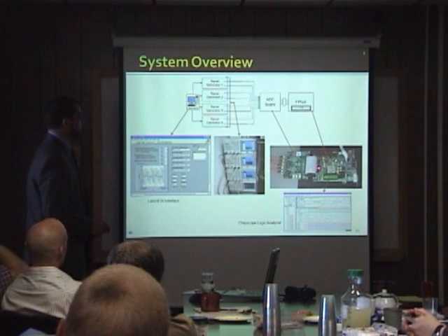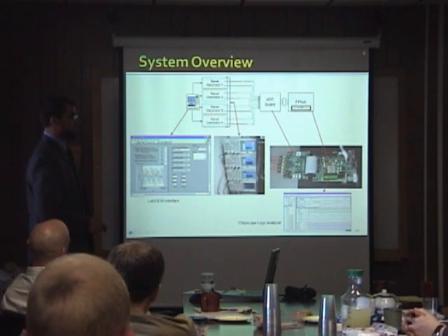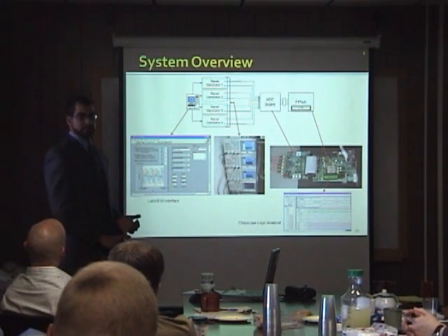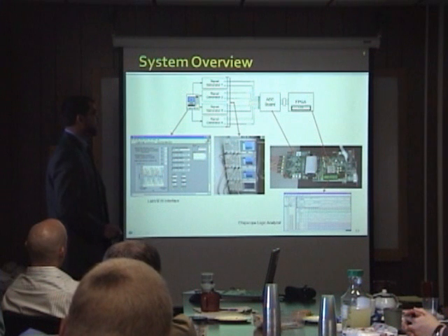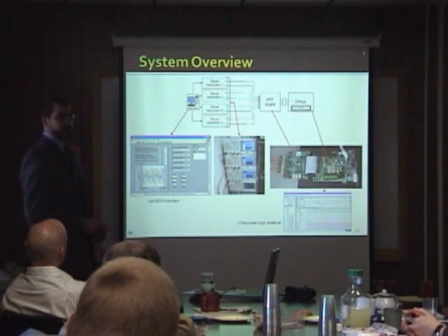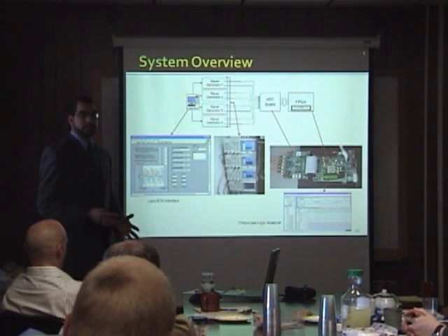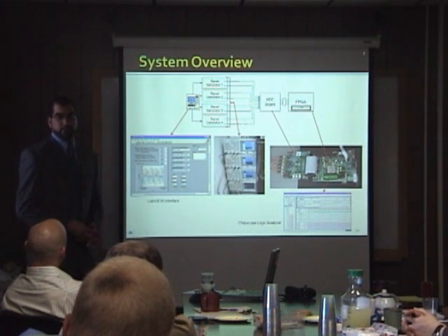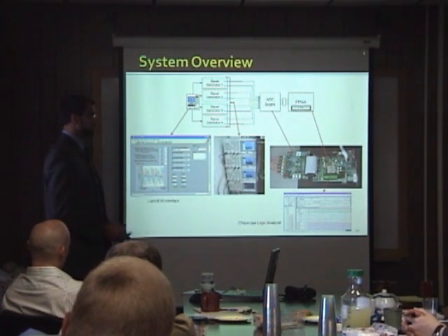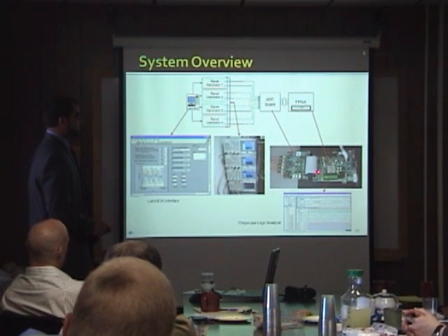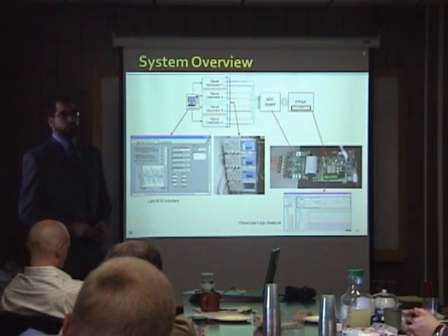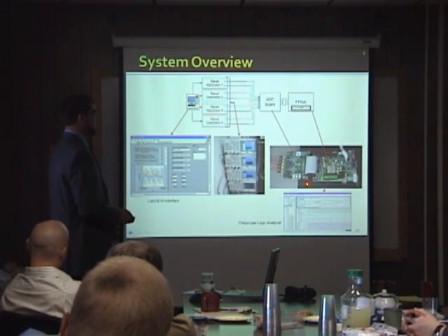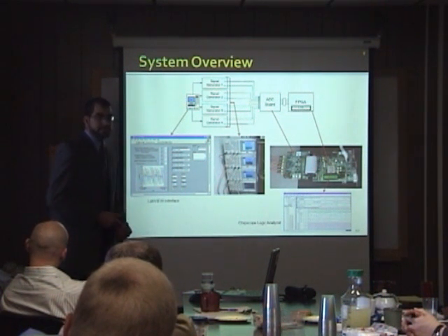And then the FPGA configures the ADC board and configures the speed, or rate, of sampling. It also sets some parameters in the ADC board, such as how we want to receive the data, in what format, two's complement or offset binary, as well as how the ADC board sends the information to the FPGA through the differential lines, LVDS differential lines. It sends them serially.